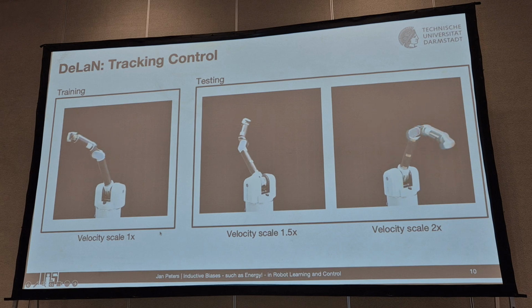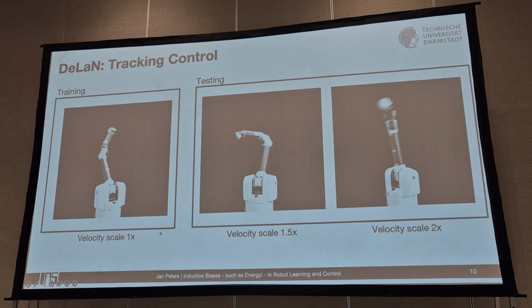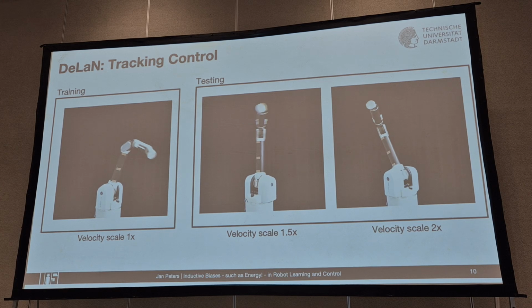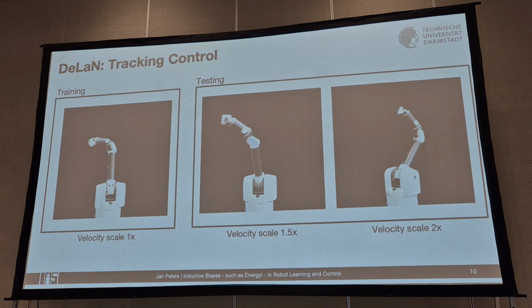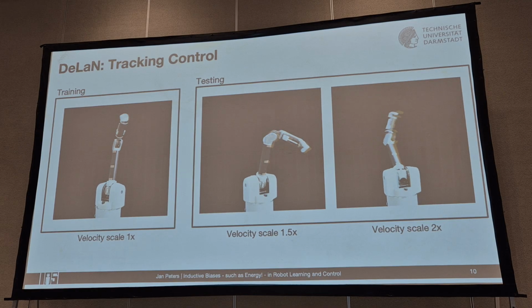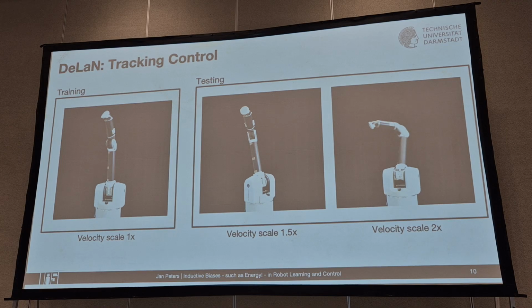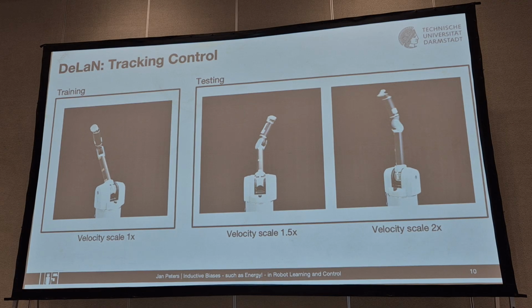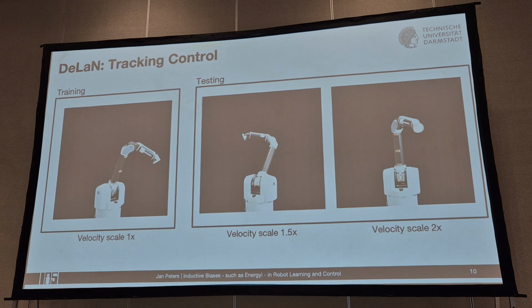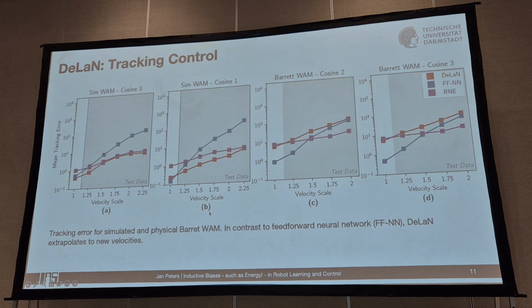This is a Barrett WAM robot which only had motor side joint encoders. So there is a flexibility in there from the cable drives which can give you an end effector error of 2 centimeters. That's one of the reasons why the Barrett WAM is only useful for either haptic-based things or if you do things with learning, because if you have to use classical approaches, you have too many unmodeled components and errors in there. But we can actually get really high tracking performance then on completely the motor side.